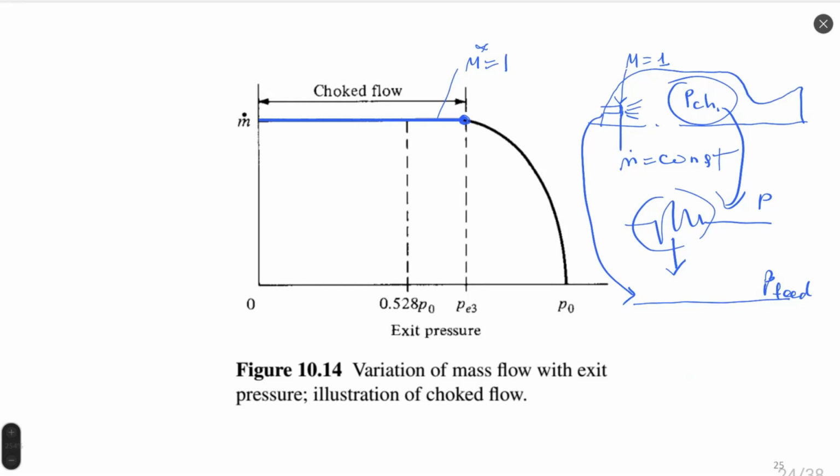It's the so-called gas dynamic separation of processes. Creating Mach 1 in some region, we prevent disturbances from going against the flow, because disturbances always propagate with the speed of sound. They cannot go against a velocity which is Mach 1 or supersonic. Propagations will always go together with the flow, and we can limit the propagation of instabilities or oscillations or any other processes.